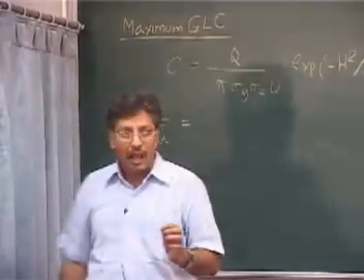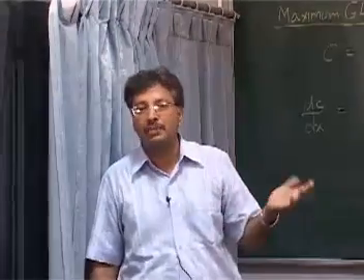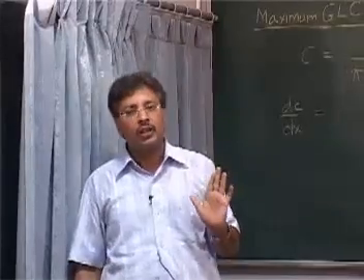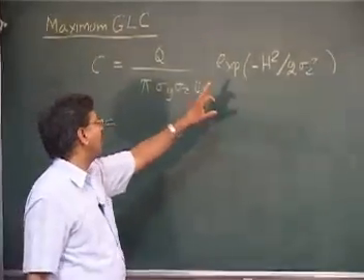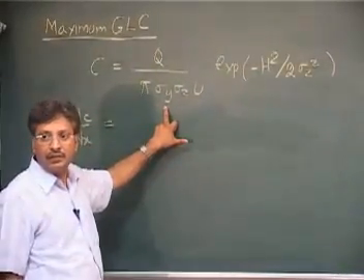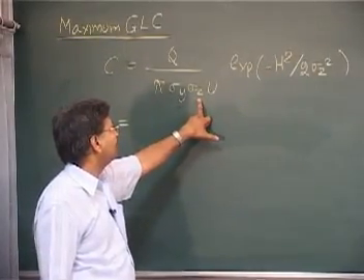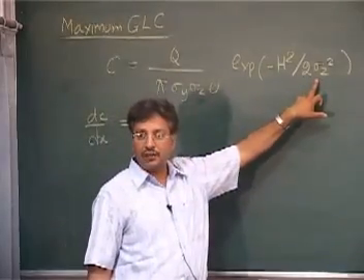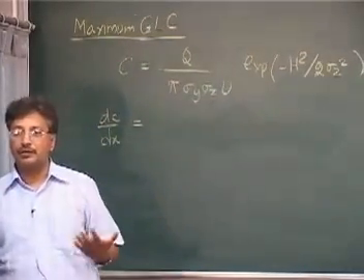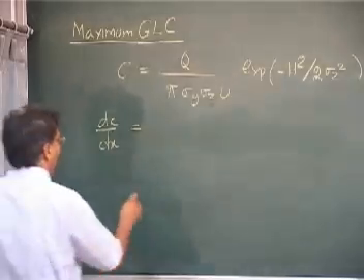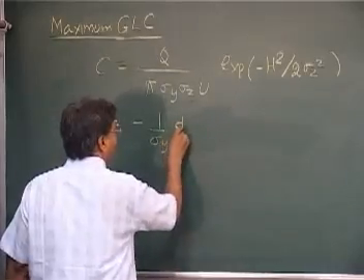So whatever the stability is, we are doing it for a particular stability. It may be A, B, C, D, E, F. Okay. So let us say whatever the stability is, I can differentiate this one, and then you find these are functions of x, right, function of x, and what else, again the function of x. Okay. If you differentiate this one, I can put this equal to 0 to find out the maximum concentration. Okay. I am writing the final form, you can see this one for yourself.